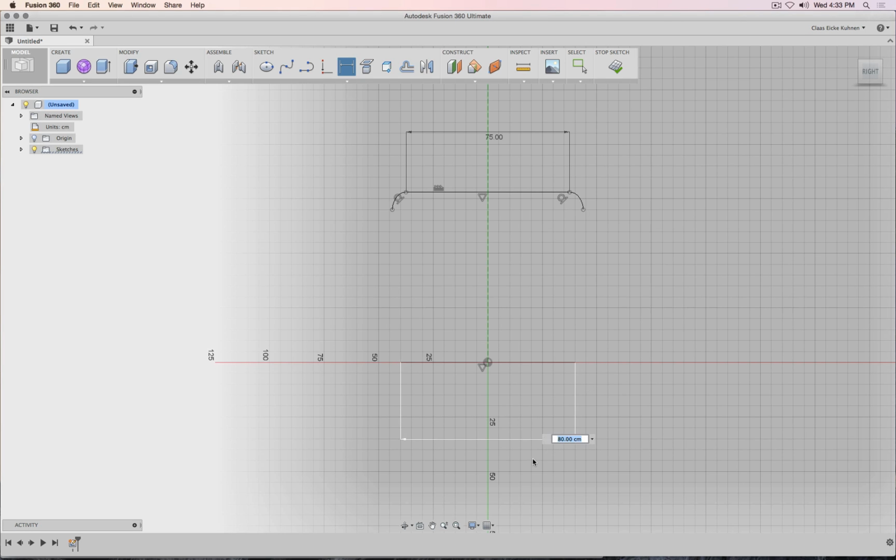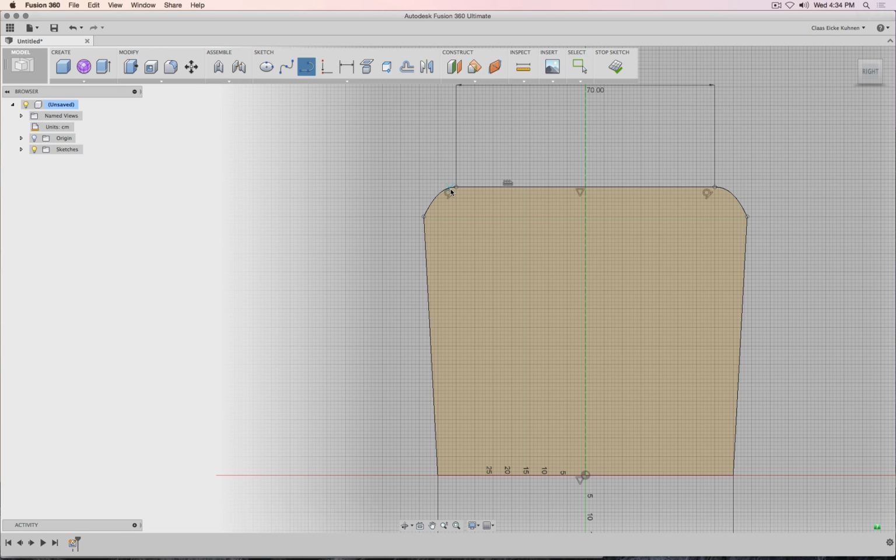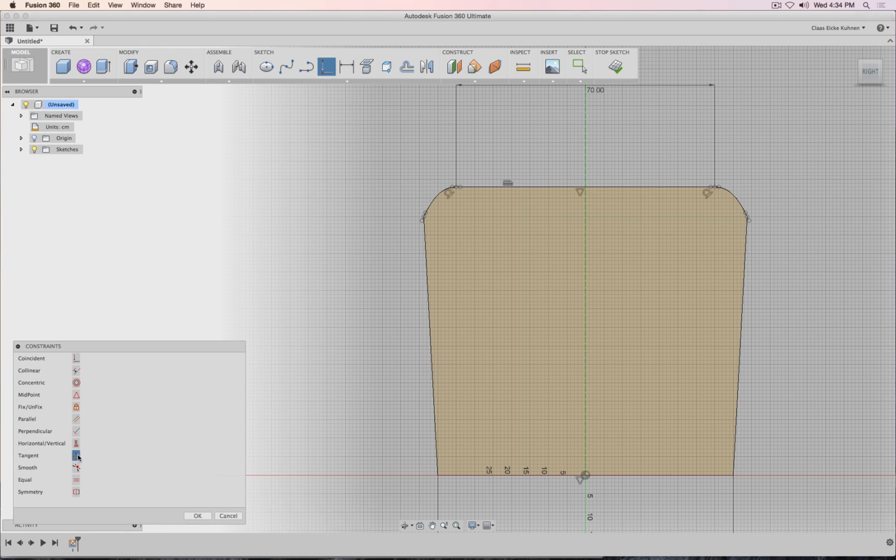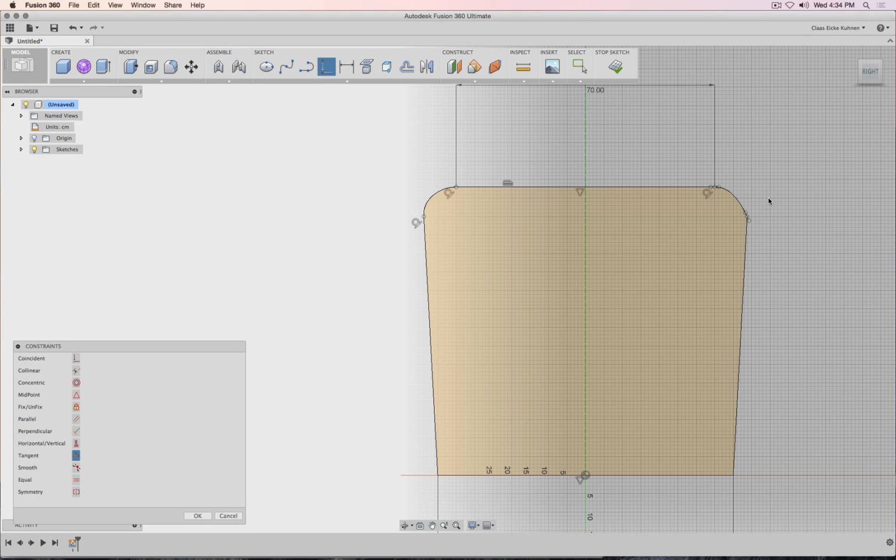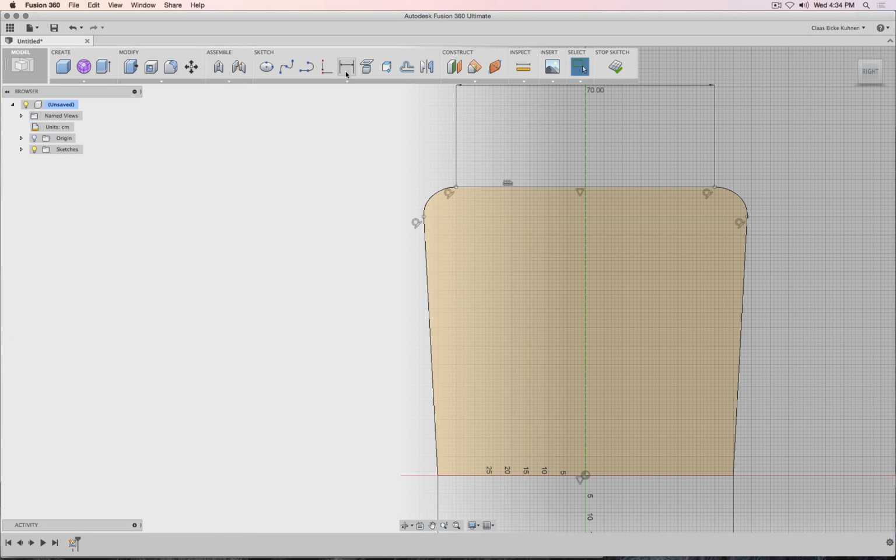So those 2 points, 60, 80, yeah, that works. So you see, redrawing the piece a little bit actually did help. So that's good. Okay, because now I might unfortunately have to redraw these lines. I know that's not really very interesting. The constraints here for the tangents here are gone, not a big deal. Tangent, this one to the line, this arc to the line, perfect.